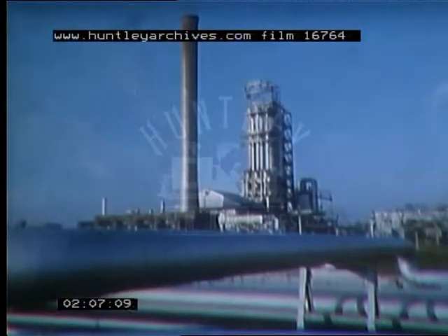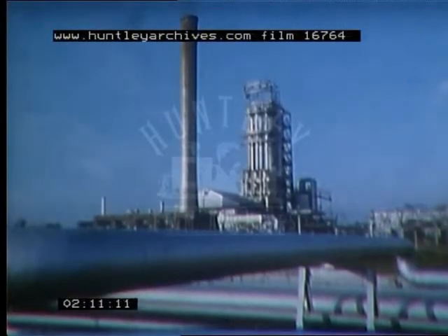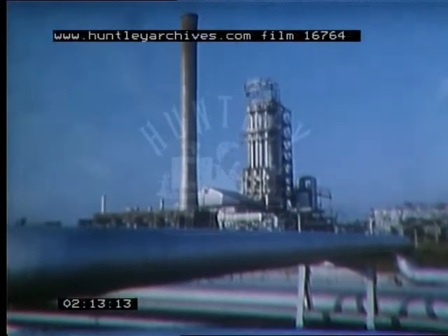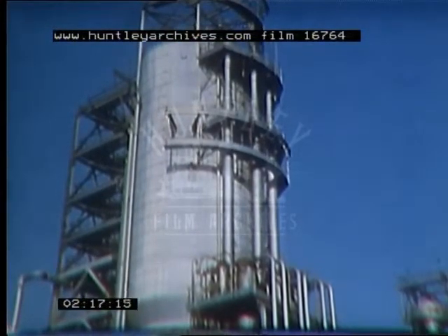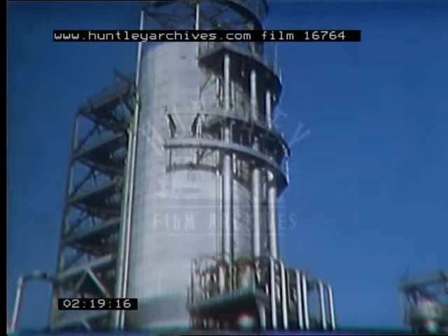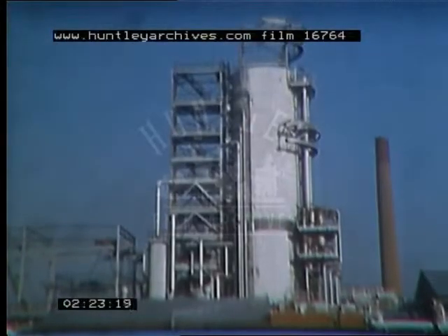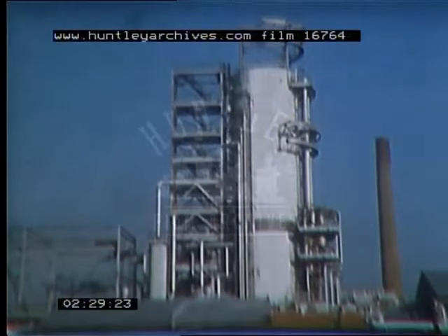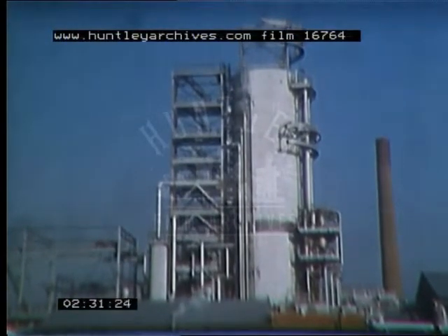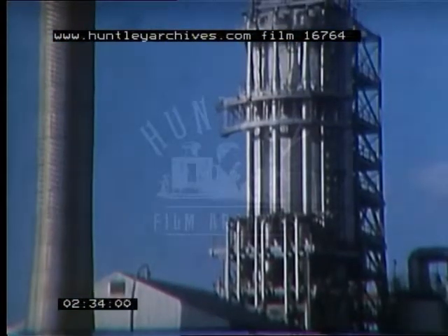In the vacuum distillation unit, the pressure in the tower is reduced by a form of pump known as an ejector. On the plant, by blowing steam through the large pipe of the ejector, the vapors are drawn out of the tower, thus reducing the pressure in the plant. The vapors and steam from the tower are blown down the big pipe to a condenser and more ejectors further down the tower, because in practice, a sufficiently high vacuum cannot be obtained with one ejector.